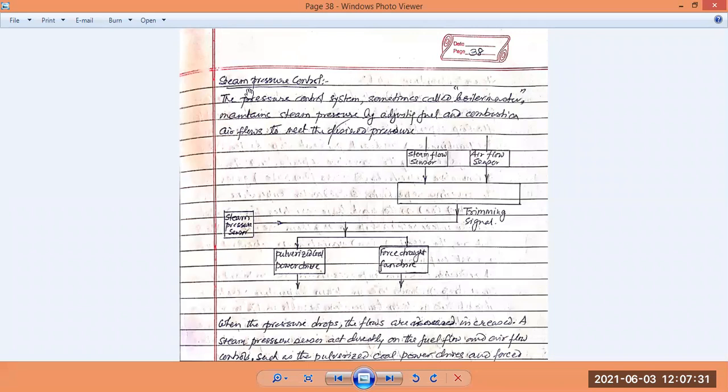To maintain the steam pressure, you have to maintain the amount of steam generated, and you can only control that by adjusting the fuel burning and adjusting the air coming in, because you mostly use almost 80% to 90% air by recycling, so you have little control over it.